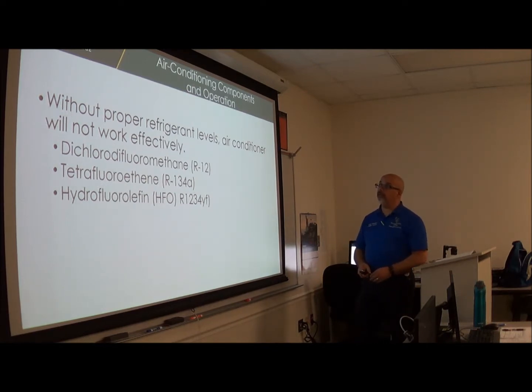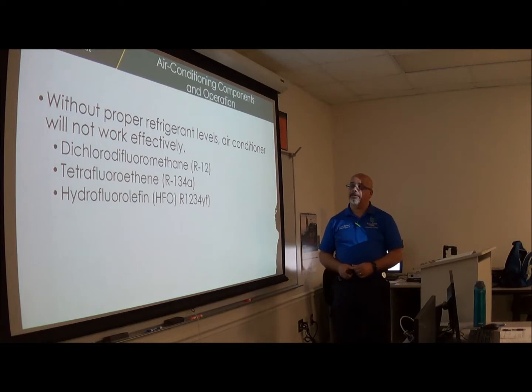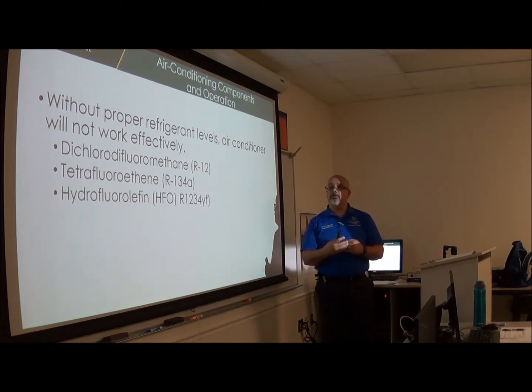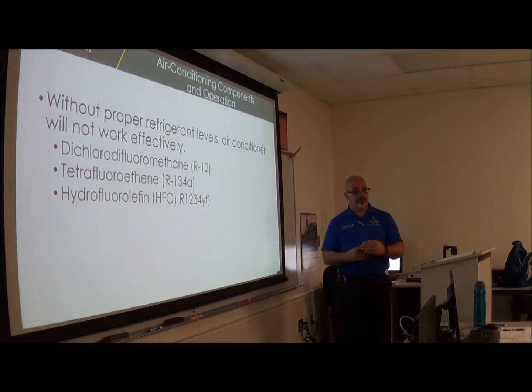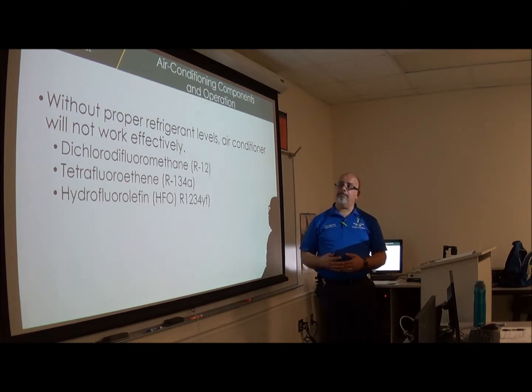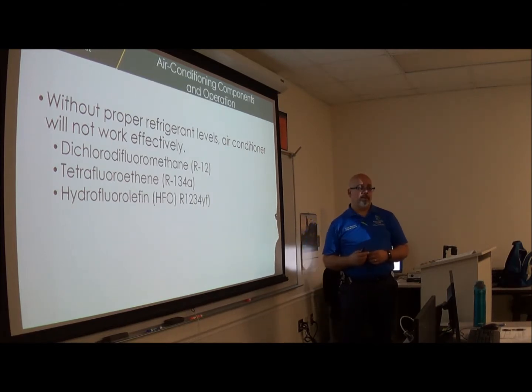So, without proper refrigerant levels, air conditioning will not work effectively. This is because if we have too much refrigerant, that refrigerant will not let the compressor work properly, because it's compressing too much, and it does not let it do its work like it's supposed to. If we have too little refrigerant, then it will not cool down enough, and you will not be receiving that cool air that you're supposed to be receiving. That's why sometimes your air conditioner blows kind of warm air, because it doesn't have enough in there.